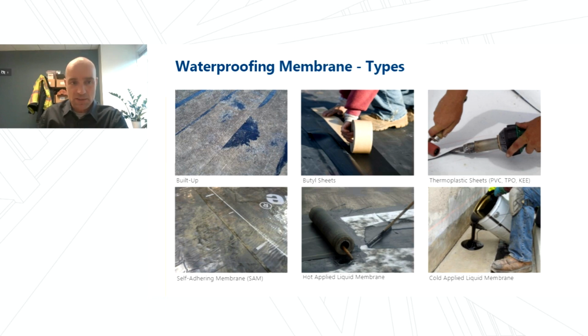What I will tell you is that I prefer liquid applied membranes because of their adhesion to the substrate, and that adhesion helps localize or contain leaks, which makes finding and repairing them in the future easier. That's a significant advantage for plazas because removing and reinstalling the wearing course or the overburden is expensive. The disadvantage of these adhered membranes is that they're vulnerable to moisture and concrete, and they're reliant on surface preparation. So those are the two items that I'd like to talk to you about this afternoon.